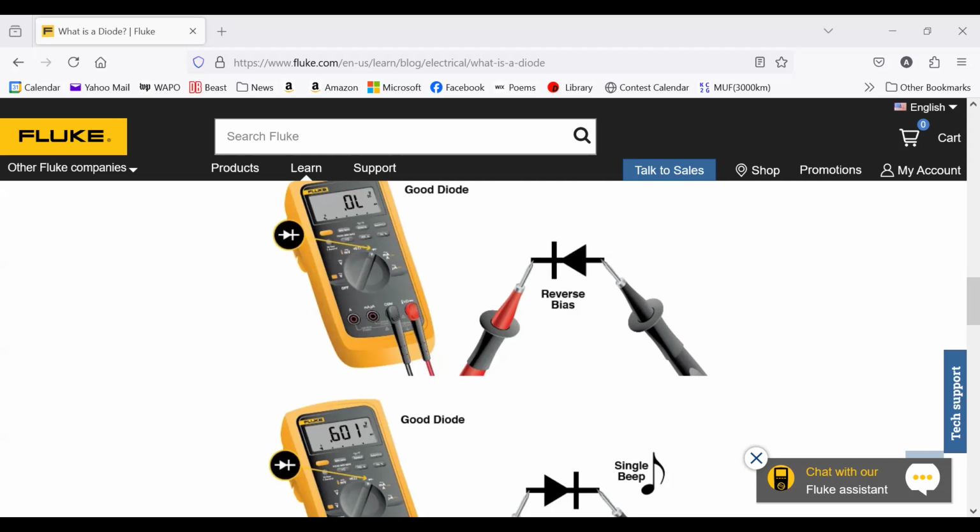The two coils on those two boxes would act as a transformer, and then the transformer would go to the diode. The diode would do its job, making this pulsating direct current, which would pulse the earphone so you could hear things. So that, all right, let's see anything else.